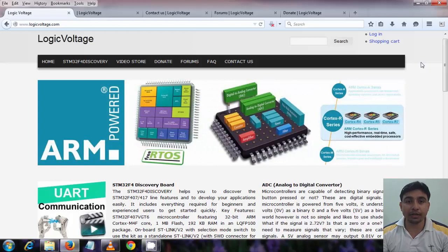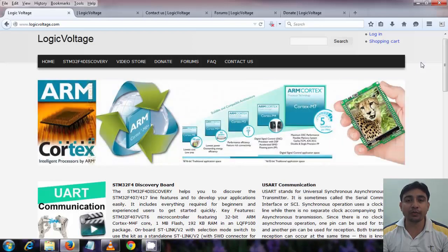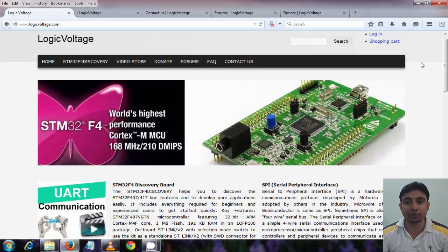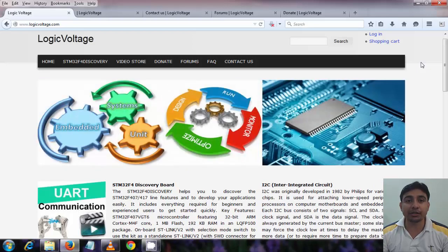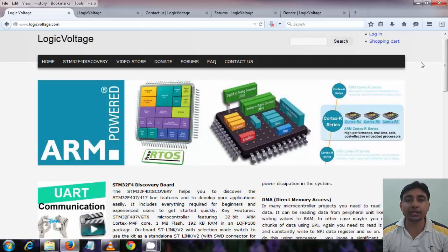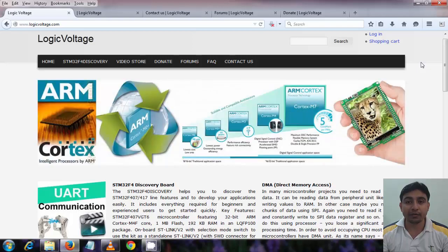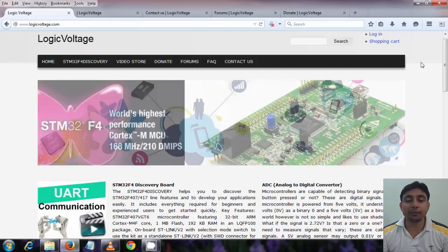For Bluetooth communication we need two Bluetooth devices. One we will get from smartphone, as nowadays generally in every smartphone we have Bluetooth. But we need another for STM32F4Discovery board. We will add an additional Bluetooth module to the discovery board and then we will control the discovery board with this smartphone. Now let me show you the Bluetooth module.